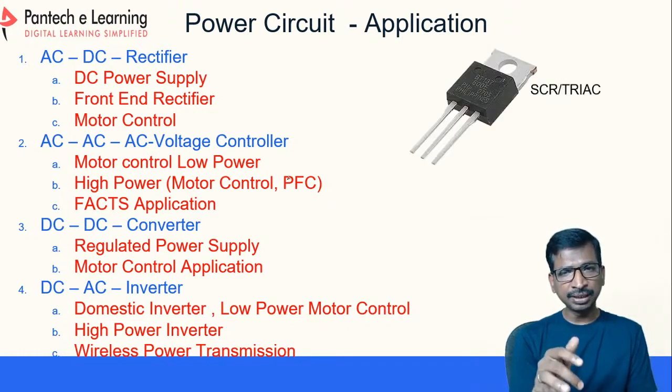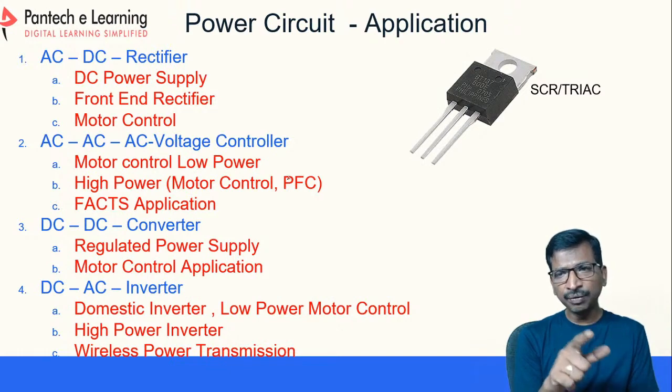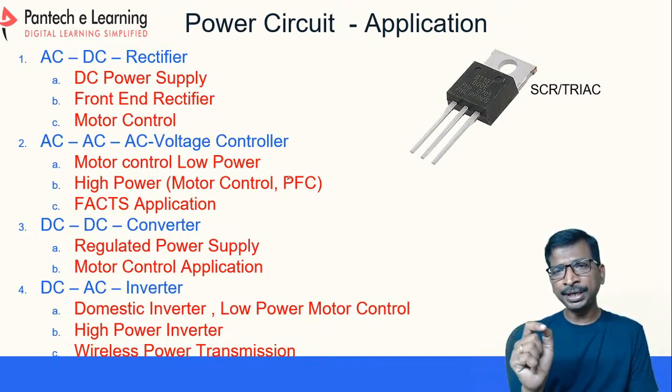So here you have to choose the device. For SCR, in the rectifier, we will use the SCR, right? So this is the SCR model, TYN612 or BT137, BT155. So these are all the switch names to choose the devices.